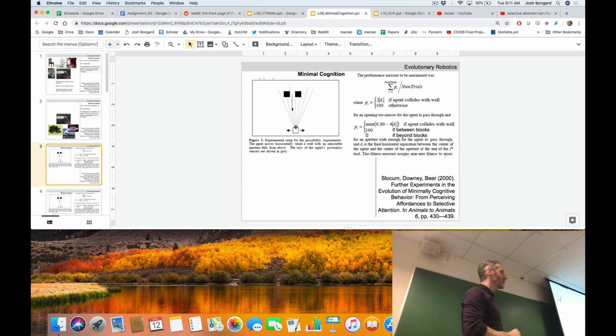So the robot knows the distance of its ray sensors at every time step. It knows nothing about blocks and distances between pairs of blocks. The neural network is going to have to infer that information from the 7 values at the current time step, and possibly, if the neural network inside this robot has recurrent connections, what were the values of these 7 sensors at the previous time step.